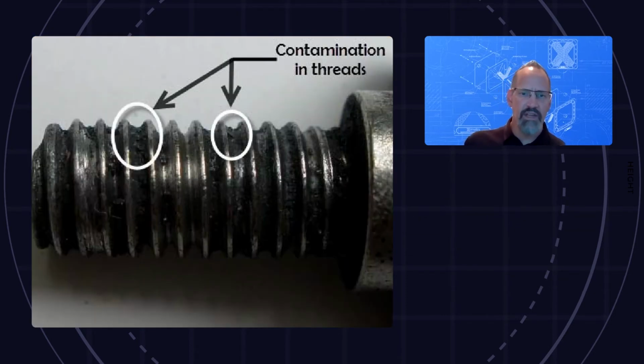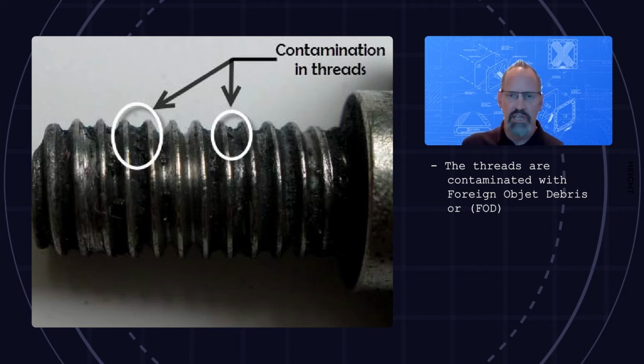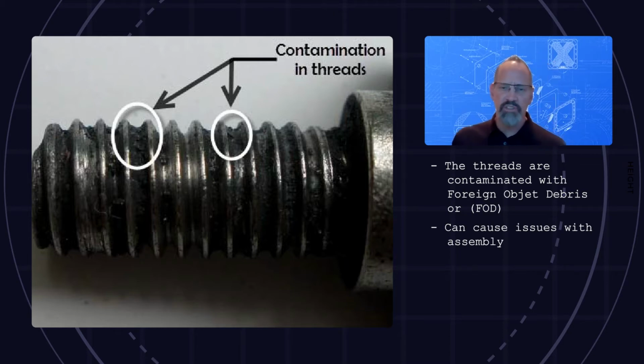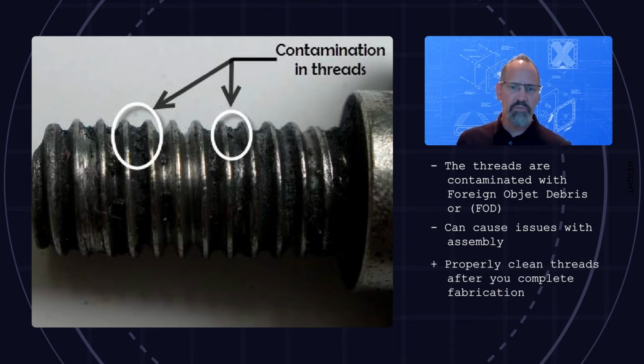In this next image, the thread is inappropriately contaminated with dirt, grease, and chips, which can lead to poor assembly, contamination of the hydraulic system, or improper torque values. This is also known as foreign object debris, or FOD. All threads should be properly cleaned before completion.